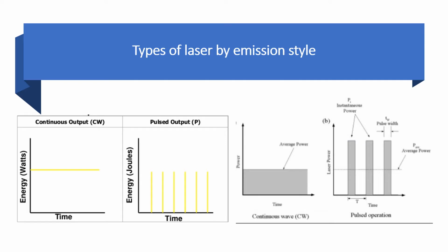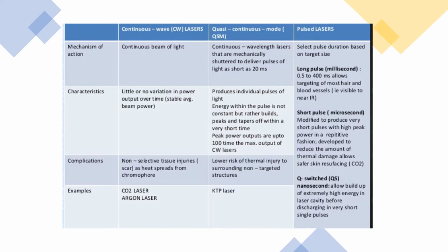As the laser beam is emitted, that can be done either as a continuous beam or in a pulse fashion. Pulse lasers are important for precision micromachining of various materials, and continuous wave lasers are important in medicine. There are two different types of pulse mode lasers. We can have quasi-continuous mode or gated pulse mode, and we can have the free-running pulse mode.